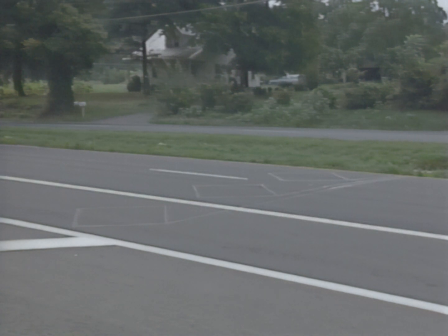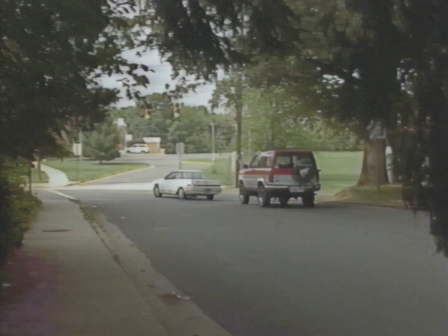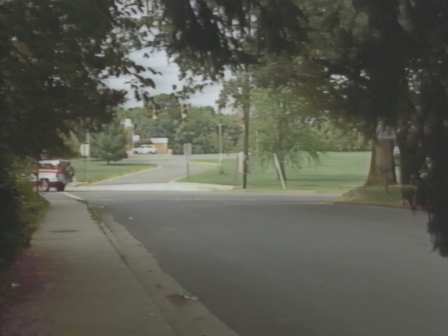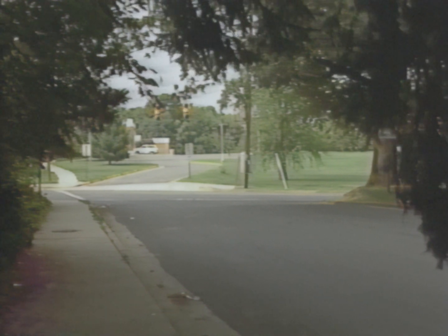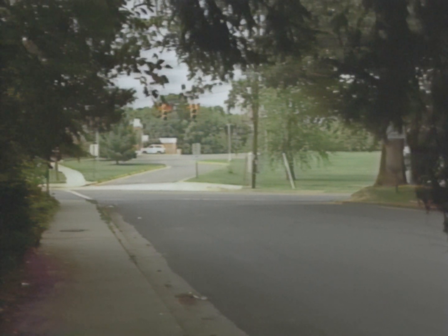Located 2 to 4 seconds of travel time in advance of the stop line, a point detector requires very specific controller timing. Appropriate primarily for low-speed approaches, this type of detection is popular for the side streets at those intersections using a more complex detector on the major arteries.